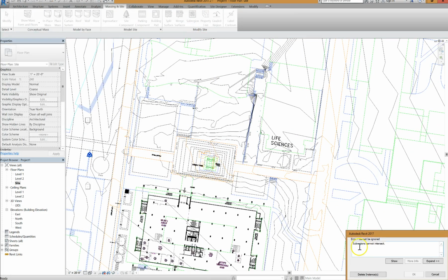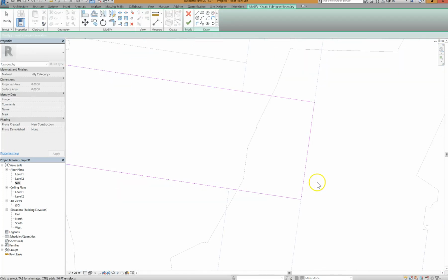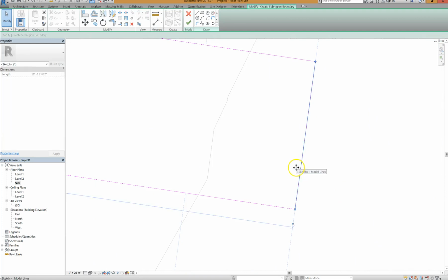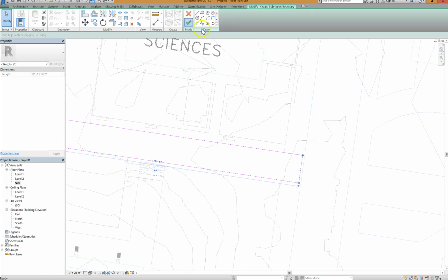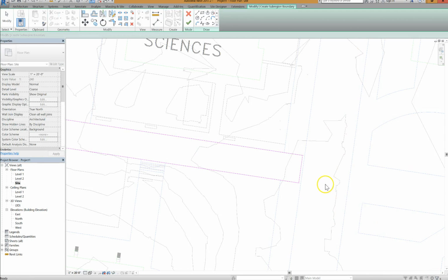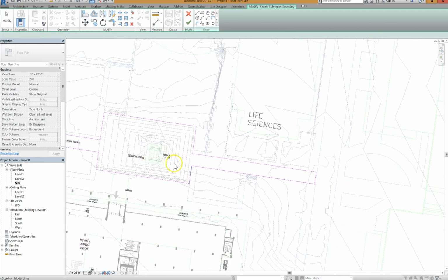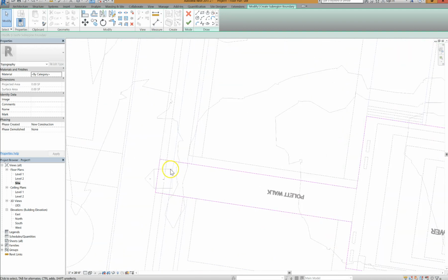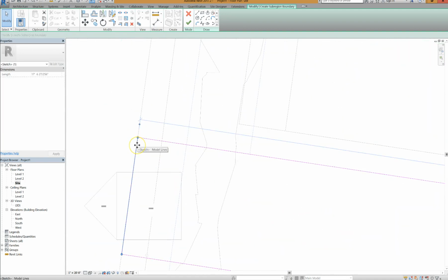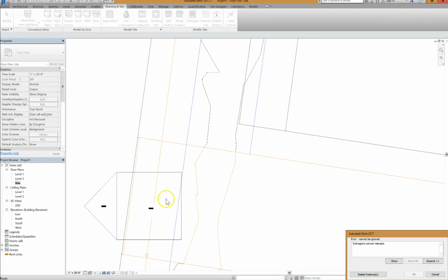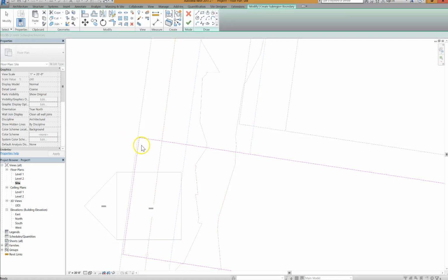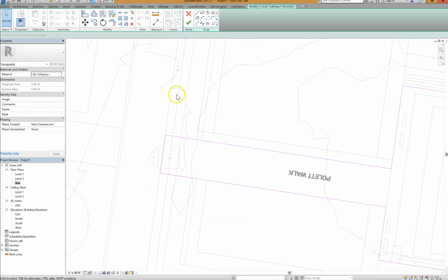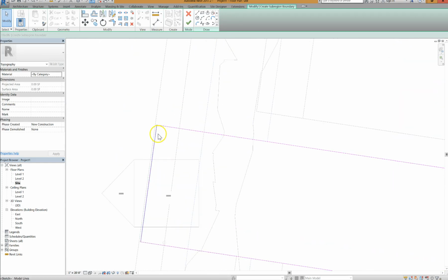Show me. Subregions cannot intersect. So that means I'm hitting one of my streets. So what I'm probably going to do just for now is drag this guy off a little bit. Is it that subregion? No, I might have been hitting both of them. So I'm going to actually tab once. You're still saying I'm hitting it, huh? Oh, perhaps that subregion goes to there. Let me see.